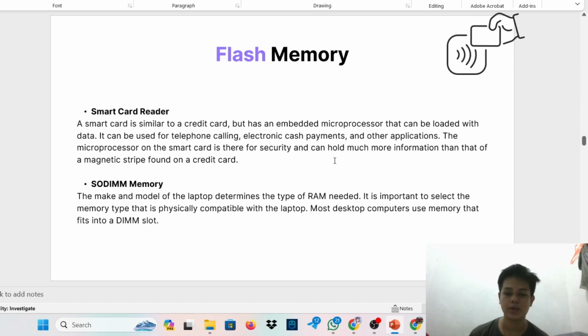Note, SODIMM can be further classified by DDR version. Different laptop models require different types of SODIMMs. Before purchasing and installing additional RAM, consult the laptop documentation or the website of the manufacturer for form factor specifications. Use the documentation to find where to install RAM in the laptop. On most laptops, RAM is inserted into slots behind a cover on the underside of the case.